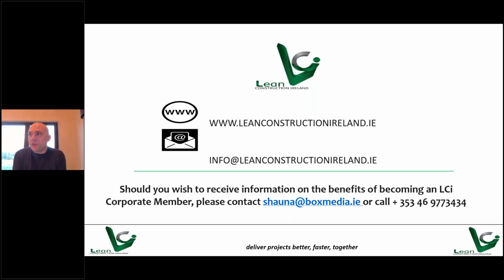When we look at things like BREEAM targets, BREEAM Excellent, there's a lot of focus in BREEAM on the M&E principles and the energy efficiency of the external envelope to achieve a rating for that building. We really need to start introducing those sorts of measures and targets for embodied carbon as well. And as I mentioned earlier, what I think is a little bit sad, and we need to push even further, is that the principles of lean design, the principles of material reduction, not only reduce the material in the building and the associated embodied carbon, but more often than not, a reduction in material use is a reduction in cost as well.